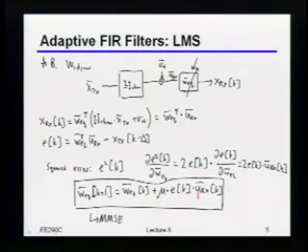But in that case, XRX should still be a vector, right? So your XRX should still be a vector, right? No, but remember, because I'm doing this as a function of k, when I move to the next k, that will still just be a single sample. So I'm taking the instantaneous error at this time, and I'm correlating it against all of the inputs that either are now or previously into the equalizer.